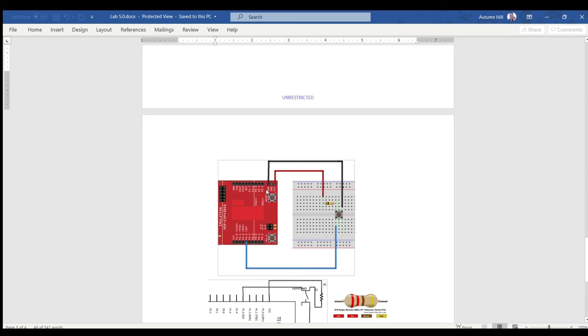You can also look back at the lecture for this week if you need some clarification on where the various wires should go and how you should be setting up a push button, but I think this should be plenty. So this black wire is being grounded. Again, any ground pin on your Arduino board is suitable. This red wire is going to a power source. The Arduino power source may not be down here. I don't believe it's the pin on the bottom right corner, but wherever the power pin is, the VCC on your Arduino board, you just want to connect to that.